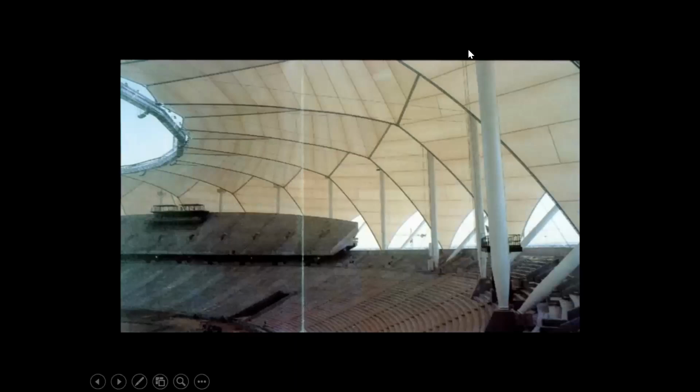Here's the inside of the stadium structure. We've got valley cables and we've got apex cables. We're always creating the reverse curvature. And so, the spans here are huge, but it's a very sensible structural system. Here you can see the masts creating the high points. They come down to pin joints near the base. And here, and all the rest is really fabric.